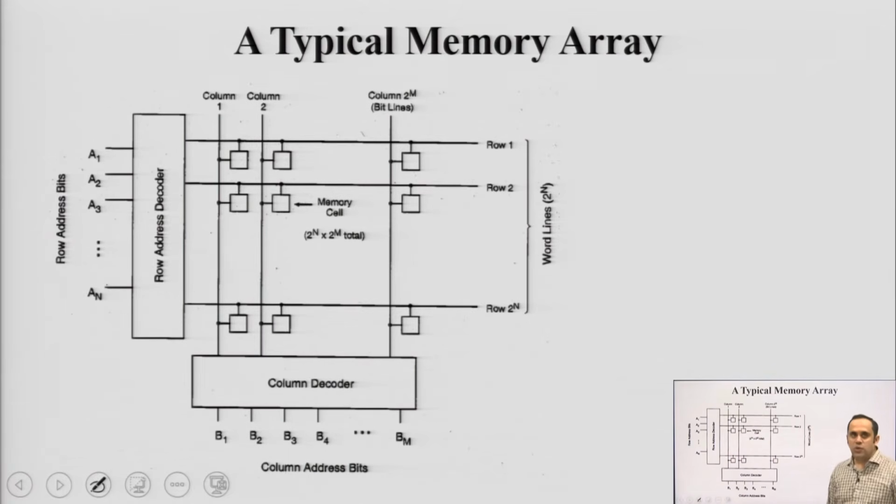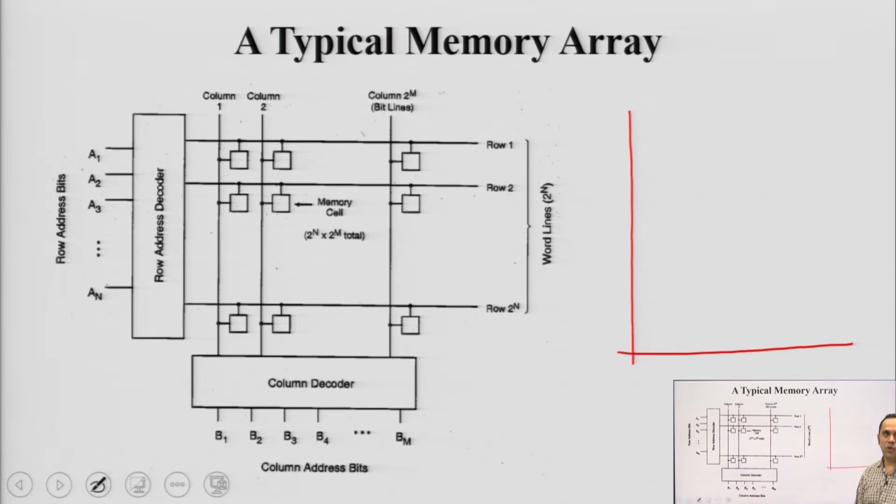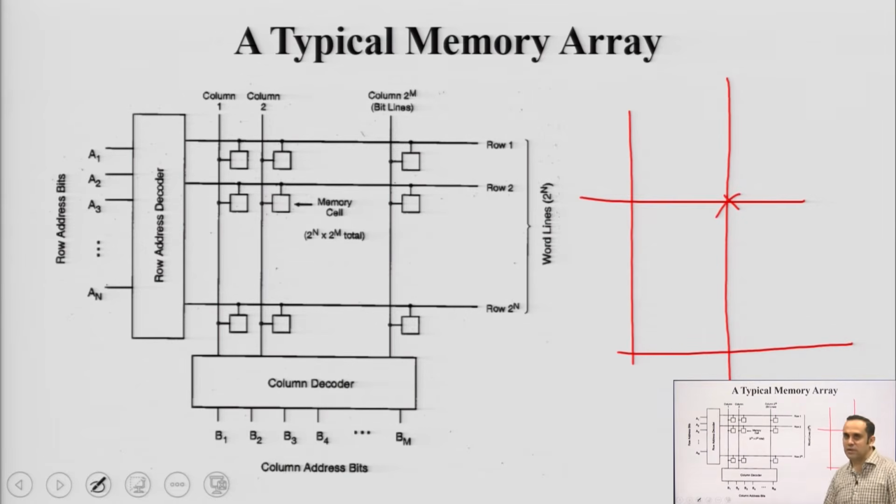You are looking at a two dimensional arrangement, where one side tells you the rows and the other side tells you about the columns. This is a row by column approach or a matrix type of design, where these rows tell you the addresses, along with the columns. So, if you start from a particular row and you hit a particular column, that point of intersection is a particular memory location or a memory cell, and each cell can store one bit of data.